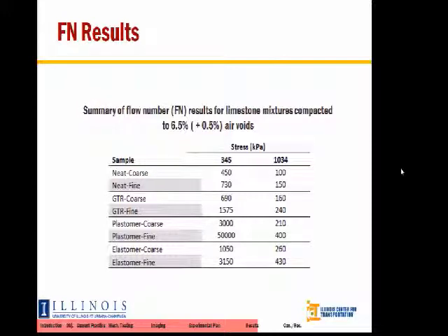performance. The one I would like to point out in this case is the lower stress level of 345 kPa, or roughly 50 psi. One of the modified mixtures ran for 50,000 cycles and did not fail. Okay? Failure, again, being defined as reaching that tertiary zone on that creep curve, where you can actually have the physical specimen collapse in front of your eyes.